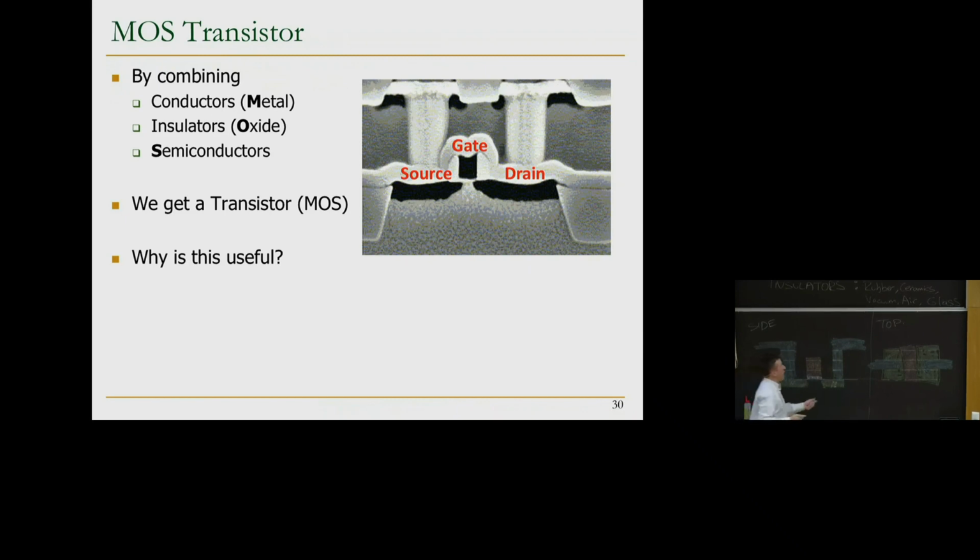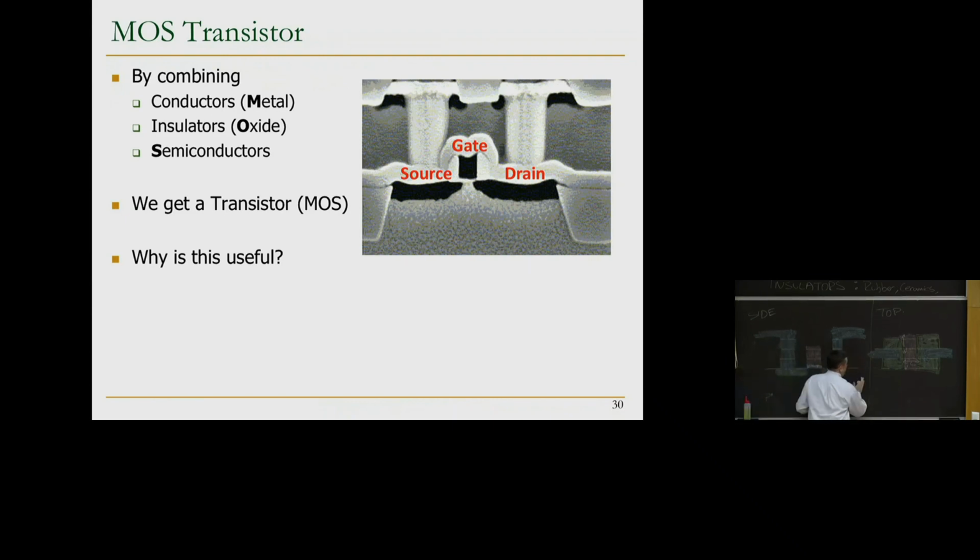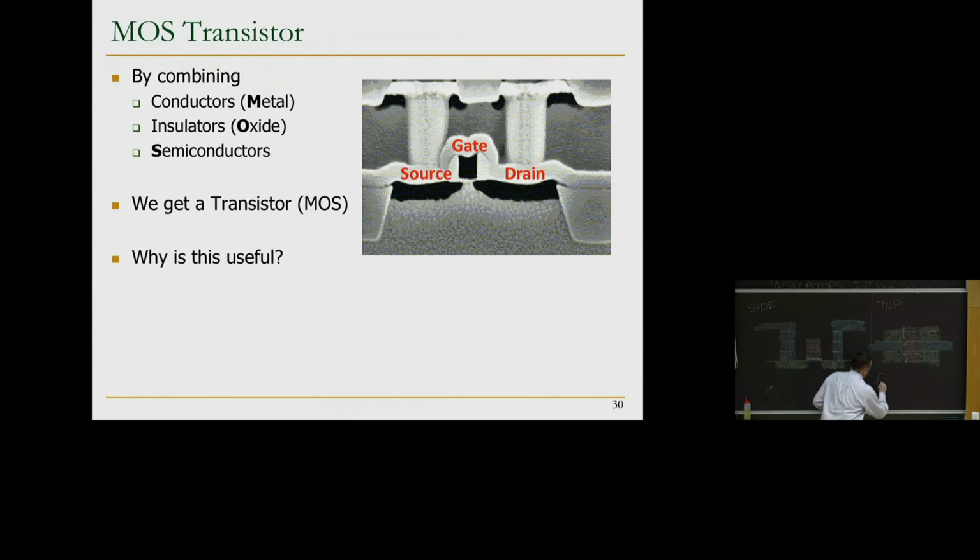If you want, let's put one more detail. We call this the width of the transistor, and we call this the length of the transistor. Okay, why do I care? Well, if you would do semiconductor device physics, and we will talk about that it works like a switch, there's a current flowing, who cares? Part of the formula has this W over L as a multiplier. There is a bunch of things which we are never going to talk about.